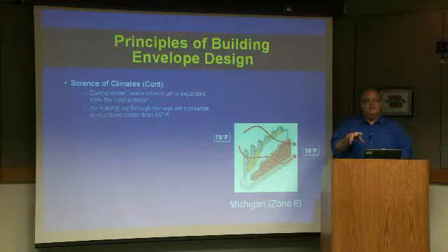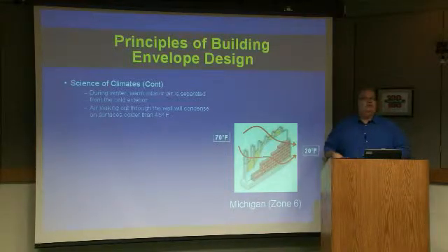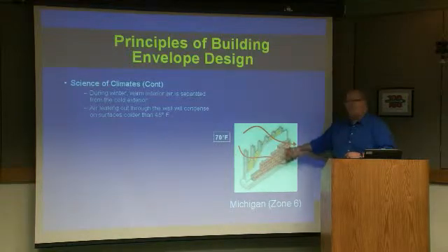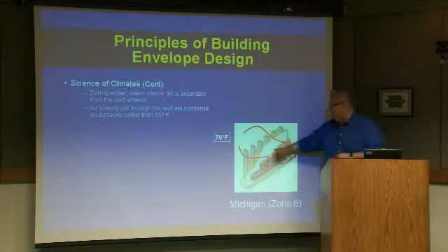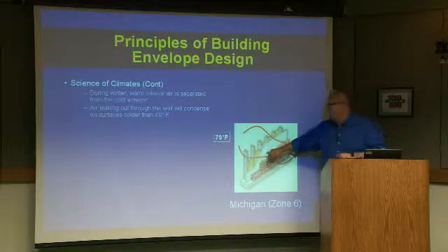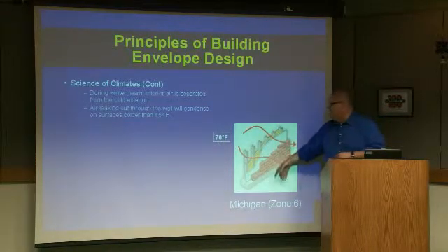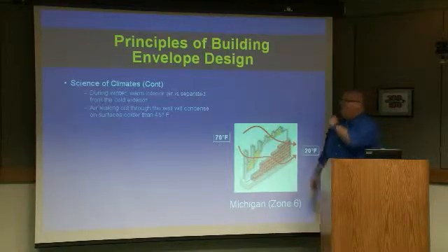That's when you react. You don't want to react to it, make it too cold, right? So in the north, we don't have typical mold problems in the winter, even though we have these really big delta T's, because the temperature where the moisture is occurring is cold. The moisture typically occurs in the outer parts of our building envelope in the north, in the winter, temperatures below 41, we have no mold growth.